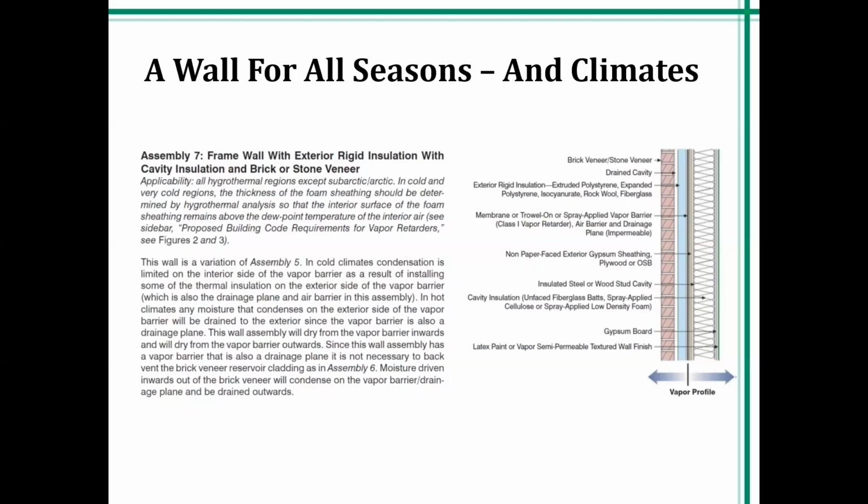But somewhere along the line, they thought about increasing the thermal efficiency of this wall. And they said, well, what would be the consequence if we bumped our 1-inch XPS insulation up to 2 inches? So they did, and there was enough money in the budget apparently, so they ran another hygrothermal analysis. And doing that, they found that their dew point got pushed further out into the cavity, away from the framing, again, away from the moisture sensitive materials. And in doing so, they reversed course. And instead of specifying a vapor permeable air barrier, they actually went to a vapor retarding fluid applied air barrier.